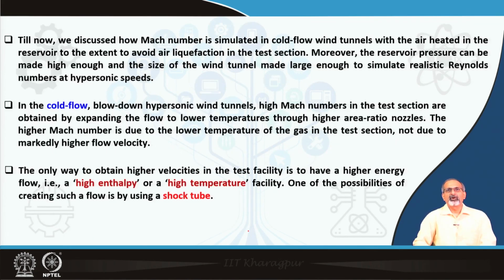Till now, we discussed how Mach number is simulated in cold flow wind tunnels with air heated in the reservoir to the extent to avoid air liquefaction in the test section. That is the threadbare requirement. Moreover, the reservoir pressure can be made high enough and the size of the wind tunnel made large enough to simulate realistic Reynolds numbers.